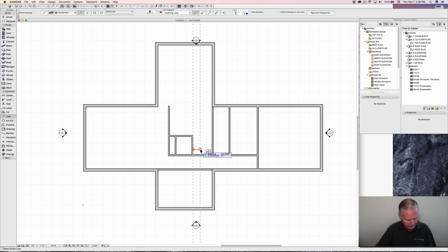Now I'm going to type D 2'1", which is going to be a countertop line. I'm going to click there and just arbitrarily pull that line up. Same thing over here. I'm going to drag it over D 2-1, click there, drag that up. Now as we drag this up, you see that guideline. I can keep it with the mouse on that guideline relatively easy.